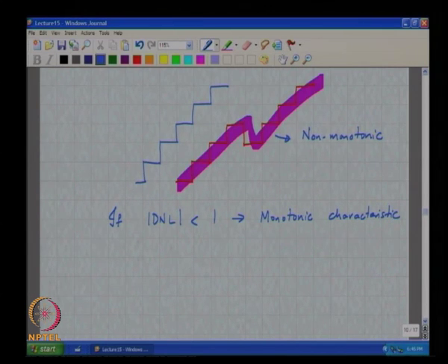What applications can you think of where it might be problematic to have a characteristic which is non-monotonic? Very good. Many times an ADC is embedded inside a feedback loop. You are measuring something, and you want to change something depending on what you measure. So, this is a feedback process, and as you all know, if you are building a negative feedback system, the sign of the loop gain must always be negative. But now if the curve is non-monotonic, then what will happen?